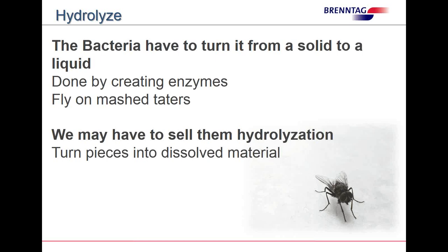So the same thing is going to be done by a bacteria. If you have a lot of solids in the water that are difficult to degrade, you hopefully will have bacteria that create just the right amount of enzymes. Those enzymes, and all it is is a chemical, not a living substance, are going to attack the substrate and basically melt it and get it into a liquid. That's what a lot of times we have to sell a plant on hydrolyzation, because we have too many suspended solids in the water. So we have to get it dissolved and we have to get it hydrolyzed.